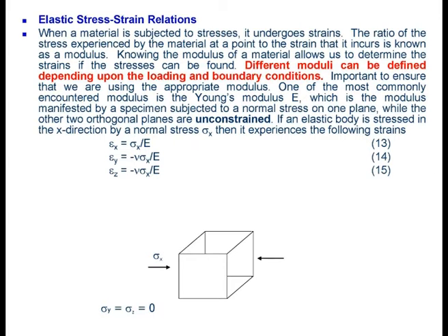Now, there's an important thing in soil. One of the things we usually do, in Plaxis, they assume this. Similarly, in GeoFEA, they also assume this convention: compression is positive in soil, quite often. It is not wrong to assume the opposite. Abaqus assumes that tension is positive. They also do soil, but they are a more general program, so they have to cater to a wider range of users. But Plaxis assumes compression is positive because most of the time soil is subjected to compression.